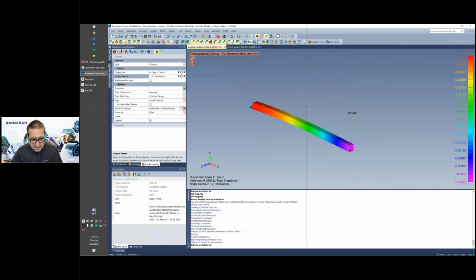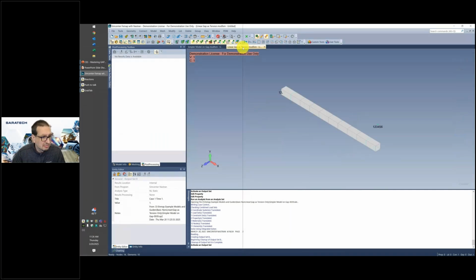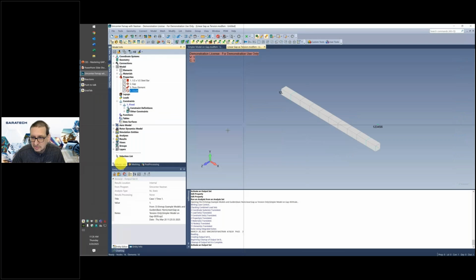With the preload force and limitation, it only really works in one direction, but with the initial gap, negative values work. So you can have both a pushing force or a pulling force, depending on whether you're using compression or tension. And it could also work as slack, so to speak. But let's take a look at linear here. Linear is a bit different in the way it behaves.